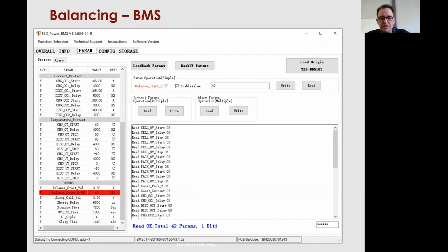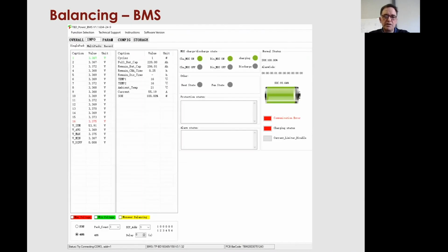So if I see about a 0.1 volt difference, I'm normally not alarmed. I know that the battery and the BMS will easily be able to handle it. It may be indicative that the DC circuitry is slightly awry, but most of the time it just means that you're at the peak. In other words, you're at about 100%, 101% capacity, and the voltages are all sitting above 3.4 per cell.